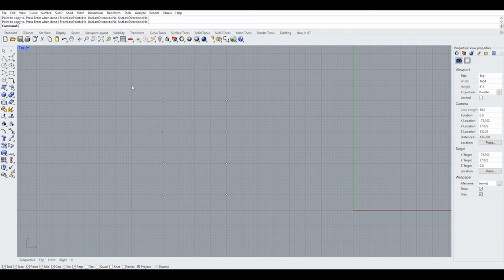Okay, so you have a set of points like I do. Now I want us to explore a little bit with our curve tools. Firstly, we're going to start off by using our polyline tool. And I'm going to make sure under my drawing aids, my point snap is active. That'll allow me to snap to this point, snap to that point, snap to this point, and snap to that point. Pretty simple, right? If we want to draw fairly boring geometric shapes, our polyline tool is very handy for this. But sometimes we want to be slightly more creative than that.